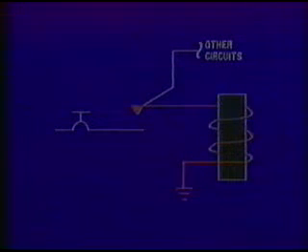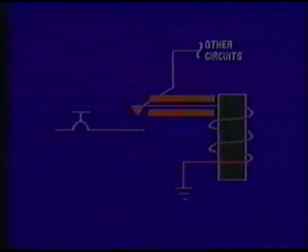This is, in fact, how a generator produces electricity, as we will discuss in our next program. Although the amount of current produced by this action is very small, the voltage can be quite high, since the numerous turns of wire collectively produce significantly high voltage. Another noteworthy property of this induced voltage is that the polarity, or flow, is backwards from what it was originally fed. Hence it wants to go back to its source. When the switch opens, it cannot get back to the battery, so it tries to use other circuits to accomplish this.